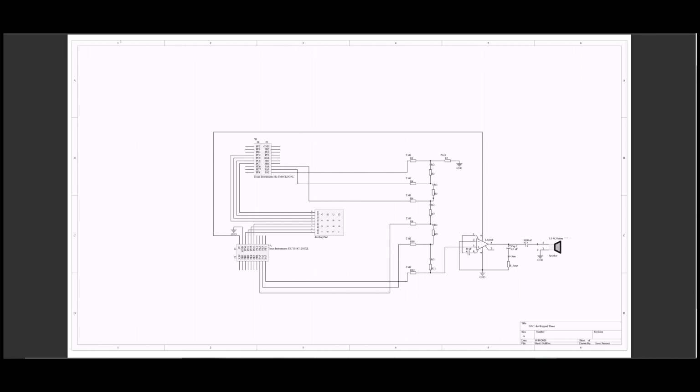In the sound file, we instantiate 3 digital waves, set up the output bits for the DAC, and initialize the SysTick. The waves needed to be digitally built are a sine wave, triangle wave, and square wave. Since we are working with 6 bits, we can count up to 64 elements. Therefore, an array size of 128 is required to build our digital waves.